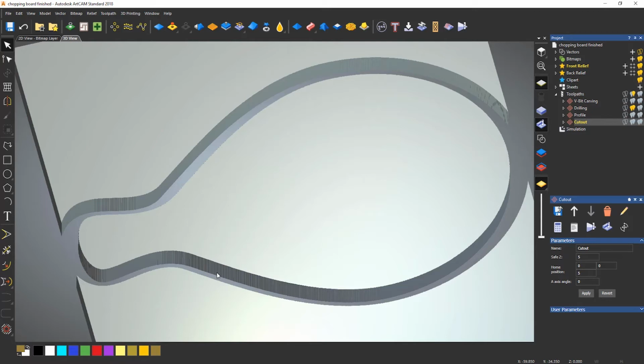And sometimes when the tool actually comes in, let's say for instance you're cutting, I don't know, acrylic or plastic. When that tool actually plunges in, sometimes it may catch fire or start burning the plastic. So you want that to start outside and then come in. Okay, so I'll show you how you can do all of this.